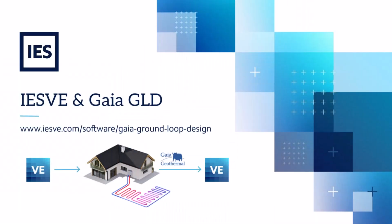That concludes the step-by-step demonstration showing the bidirectional data exchange workflow between IESVE software and Gaia Geothermal's ground loop design software. As a sign-off note, I would like to say that accurate right-sizing of the building's heating and cooling loads is critical to an optimized and right-sized geothermal heat exchanger design, because oversized heating and cooling loads may result in oversized and expensive geothermal systems. This data exchange between IESVE and GLD should help designers to optimize the overall system design.